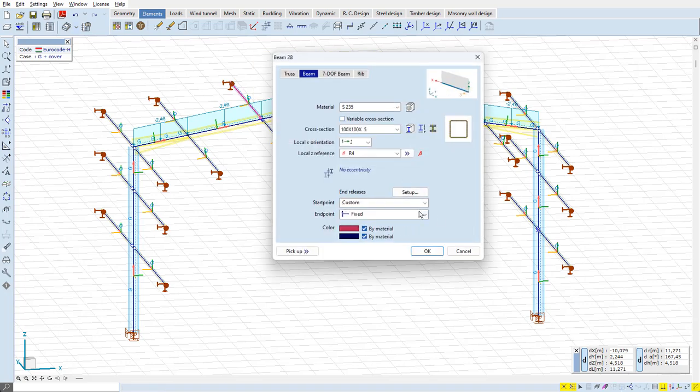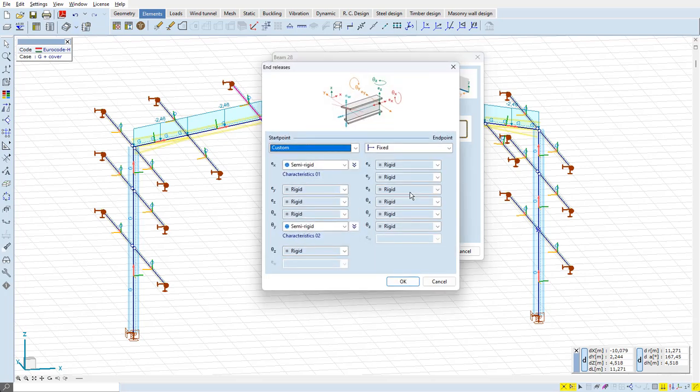To present the actual differences, it has semi-rigid connecting stiffnesses in the purlin's connecting end in two components. First is the displacement in the direction of the purlin axis. This means lateral support to the rafter. And the second is rotation around the purlin's strong axis.